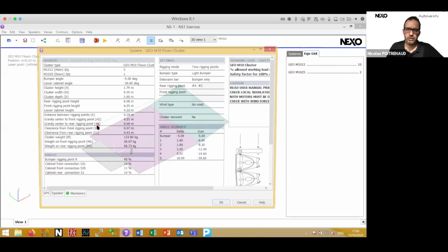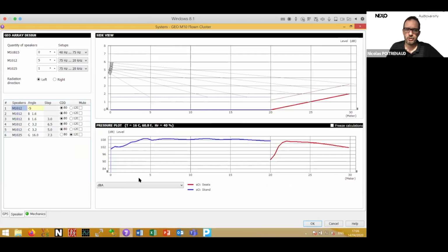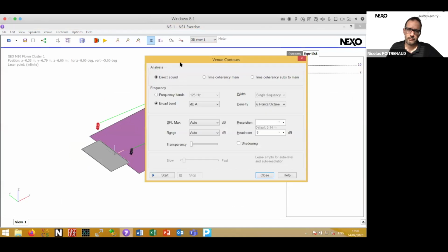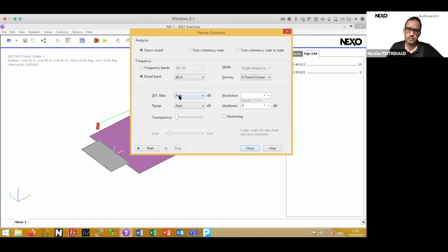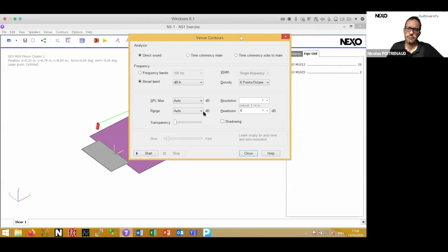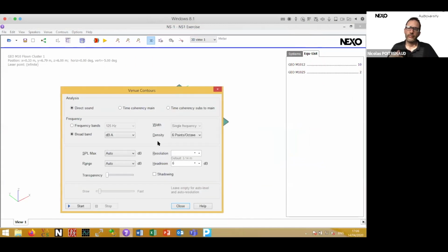Yeah, so if you want to change the range of pressure, when you run this calculation, you see that you can change the value. So by default, if you do nothing, it will take the highest value and get the highest value as the very red color, the red color for the maximum. If I want to change that, I can specify any value.